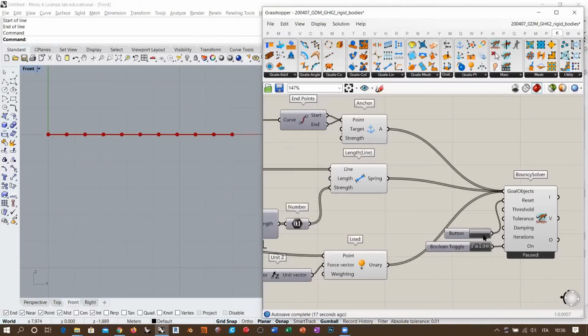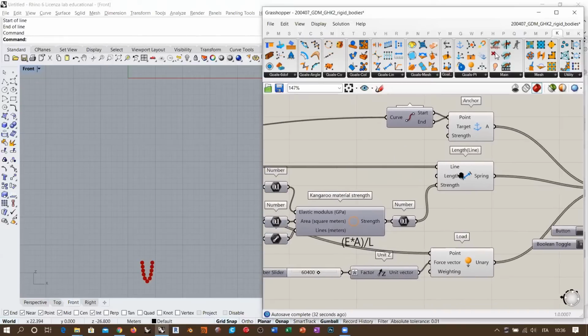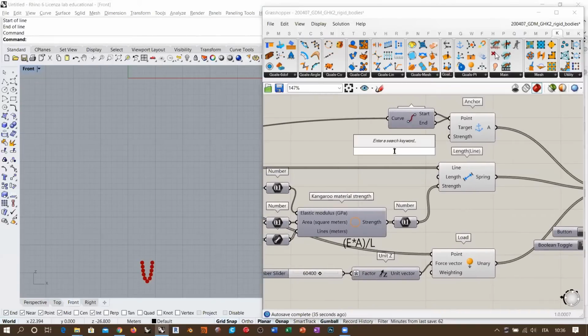So you will see that if I fire the simulation, the only thing that happens is that the anchor points cannot bear with this load that we are applying. Okay, so you see that these are the anchor points. They moved down from here to here. Now, in order to avoid this, I'm going to take, for example, a value like 10 millions, which is more or less the value that we have for the elastic strength.